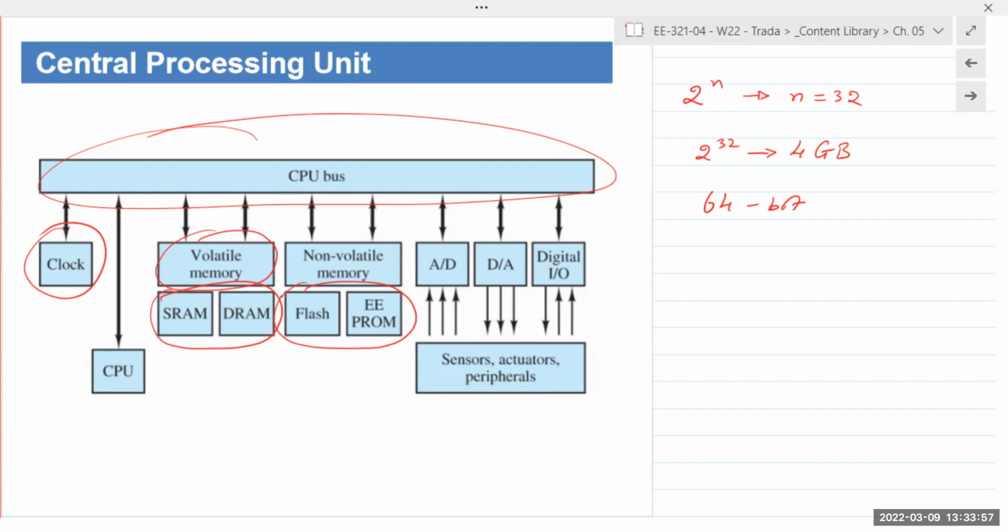And of course, the other kinds of memory are the NAND and NOR-based flash memory, which we know as solid-state drives, SSDs, which is inside most laptops and most desktops nowadays. Okay, those are all flash-based memory. They are non-volatile memory, meaning you can take the power out, and they will still hold the data. They will still hold the charge inside the devices, meaning whatever state the transistor is left in, zeros or ones, will stay in the memory even if the power is off.